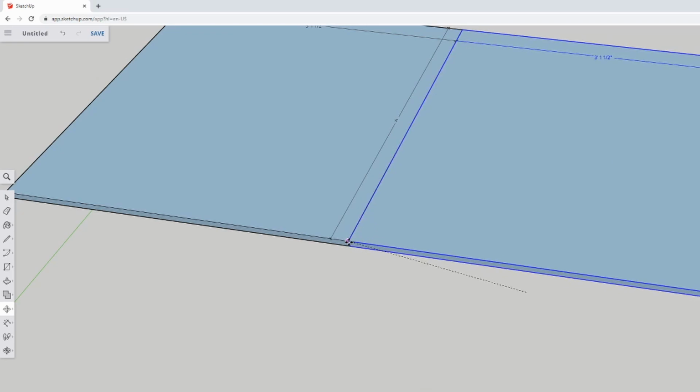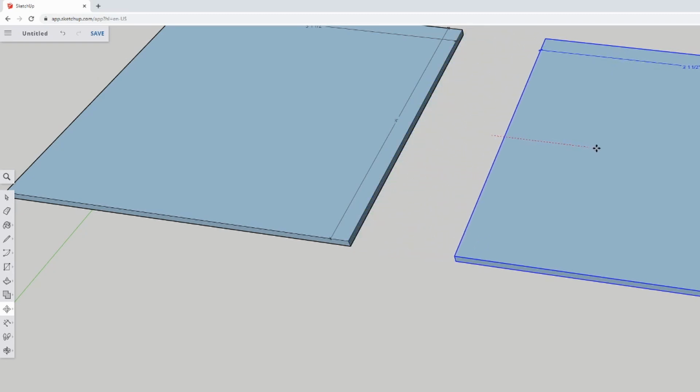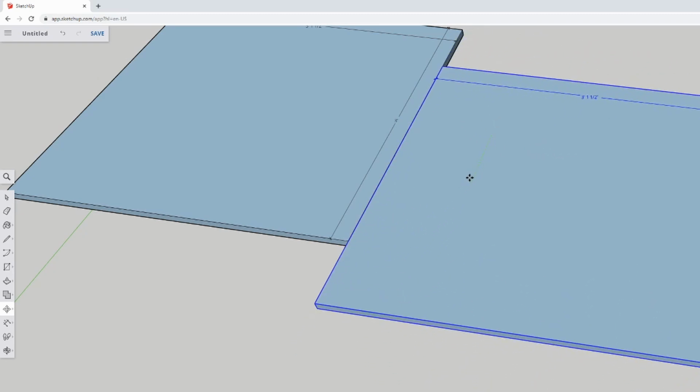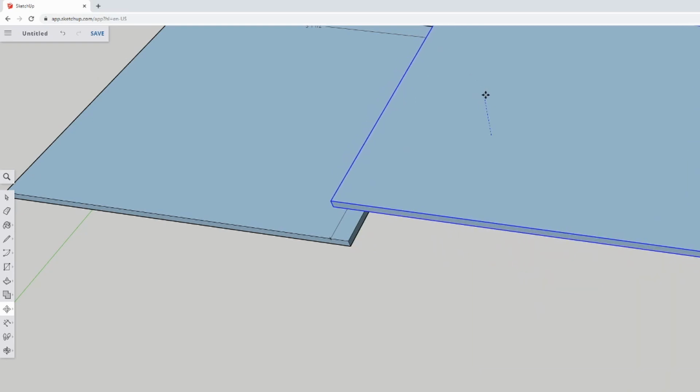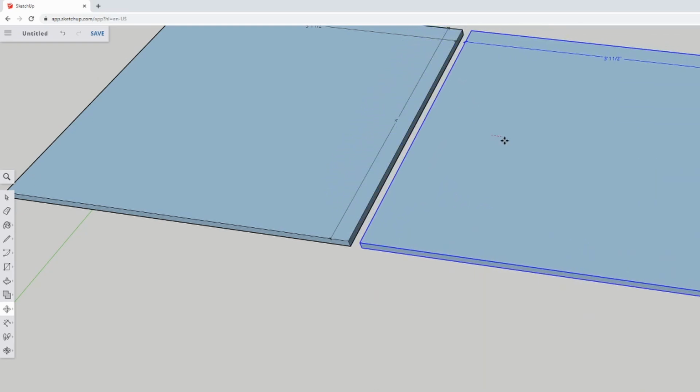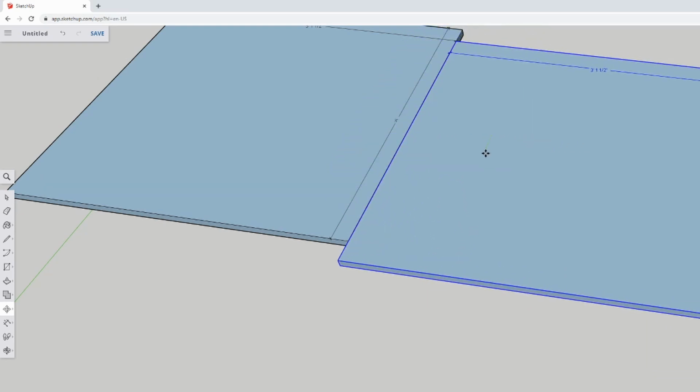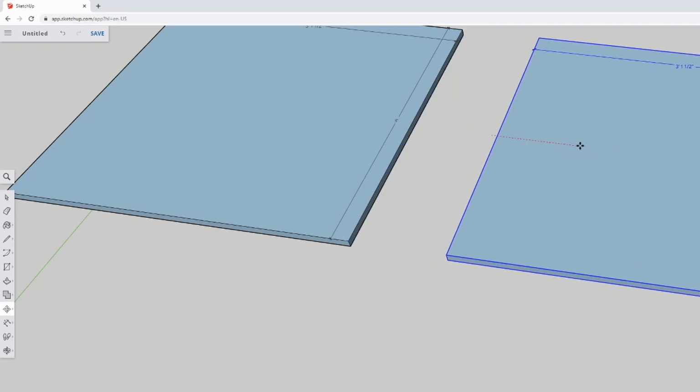So I'm just going to snap this here as the other piece, and then once it's snapped, I can click on it. And if you drag something along the different axis points, you'll see if I go along the blue, it moves it up and down. Red, it snaps it right to left, and green front to back. Now I know that if I move this along this red plane, that it's parallel to this, but it's off to the side so I can work with it.